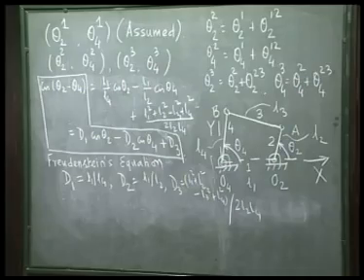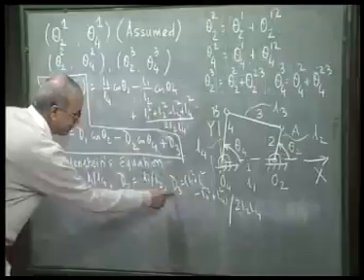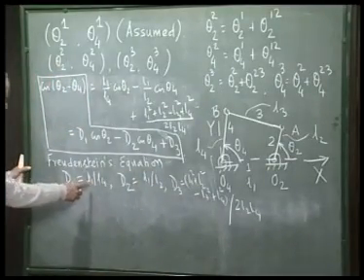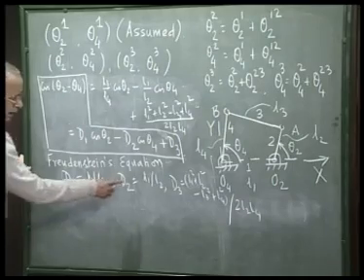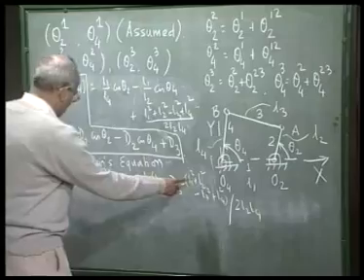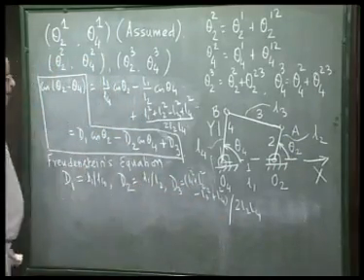Now, thing to note is, from these three design parameters, once we have solved, I can get the link length ratios, namely L1 by L4 from d1, L1 by L2 from d2, and substituting for L2 and L4 in this equation from d3, I can get L1 by L3.